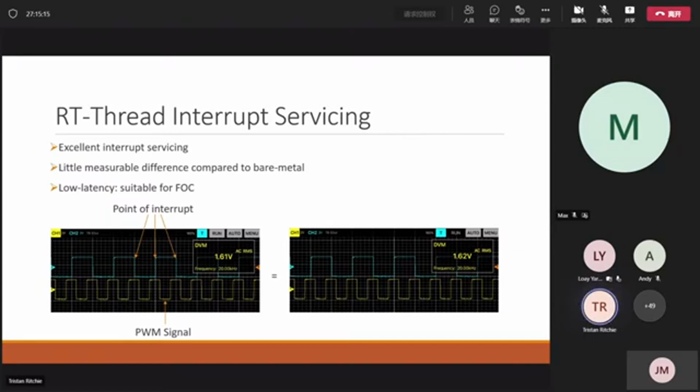However, this isn't quite the whole story. Using an RTOS generally means that we'll be working in a multi-threaded environment. And of course, most of the kernel code, such as scheduling or manipulating concurrency primitives, will execute with interrupts disabled. And this will certainly impact the latency that we've measured here by introducing some delay of some magnitude. And so it'd be quite interesting to actually measure that.